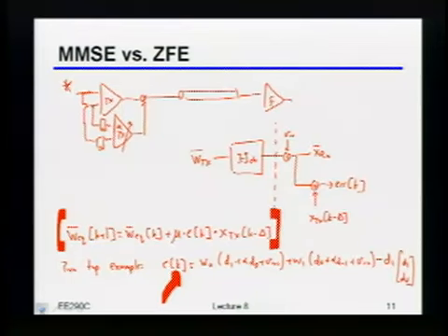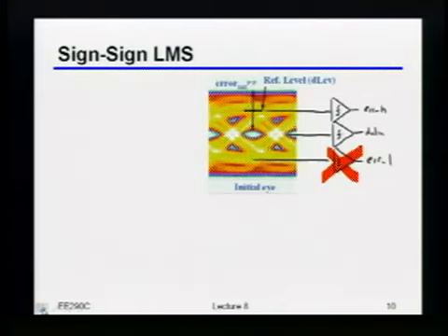That's my last slide here. That's a great question. It does bring up another point which I want to mention, which is that especially if you do these sine-sine types of loops, your updates are really coarsely quantized, right? So you're not going to want to just directly apply them, but somehow average them out even further. By the way, you don't typically want to run this thing at 10 or 20 gigahertz or whatever it is.